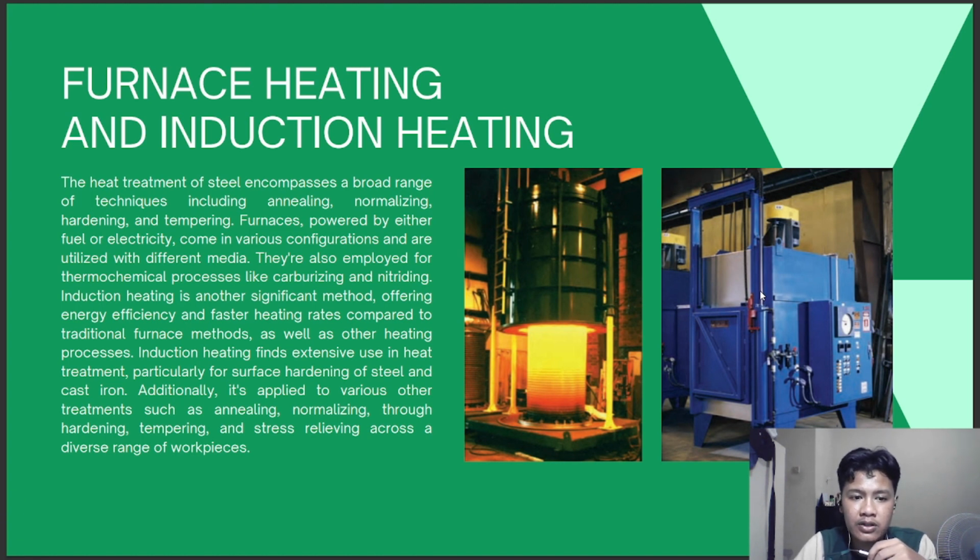Induction heating is another significant method offering energy efficiency and faster heating rates compared to traditional furnace methods, as well as other heating processes. Induction heating finds extensive use in heat treatment, particularly for surface hardening of steel and cast iron. Additionally, it's applied to various other treatments such as annealing, normalizing, through hardening, tempering, and stress relieving across a diverse range of workpieces.